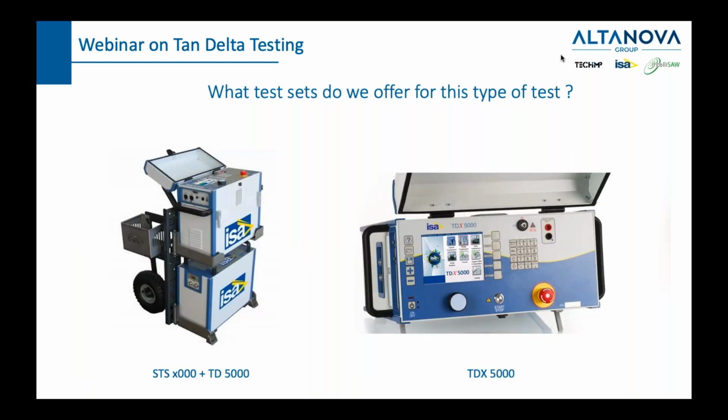So here you can see some of our test sets, the STS and the TD5000. The TD5000 is an accessory for tan delta, and also the TDX5000, which is a single device used to test tan delta. They both generate up to 12 kilovolts, a maximum of 300 milliamps, which is more than enough, because you would normally generate maybe up to 10 or 20 or maybe 30 milliamps when testing a transformer. When testing a cable or when testing a generator or a motor, that can be more.